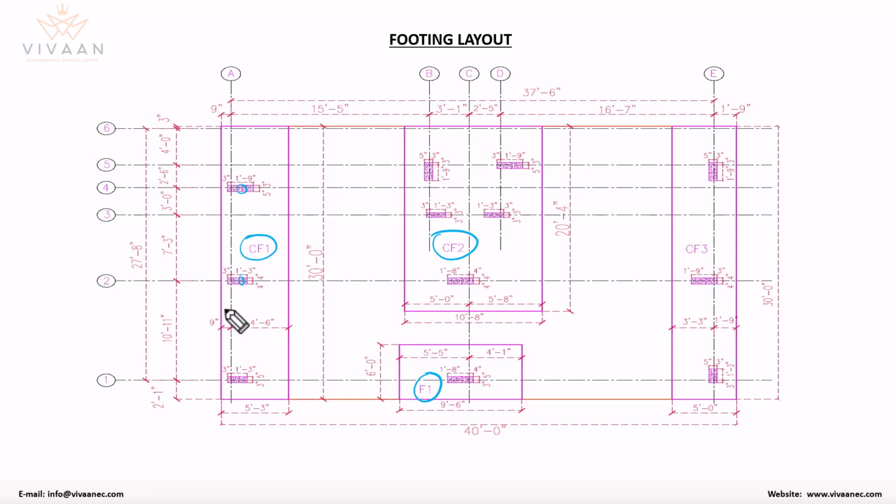So when you're going to purchase the steel or the rebar from the shop, you need to mention that you want 550 grade steel D, 550D. D is for deformation. Basically, as the strength of the steel increases, the brittleness also increases, so to maintain flexibility there, to make the brittle structure take more loads and have more elongation capacity, so more deformation.